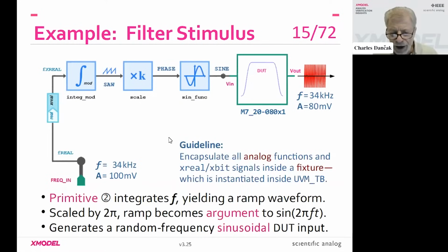And so as a guideline, we recommend encapsulating all the analog functions, instrumentation, and signals of XReal type, or its digital counterpart, X-bit type, inside this fixture submodule, which we can, as we'll see later, instantiate inside the topmost testbench.